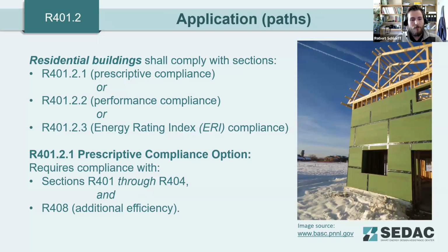Moving on to more of the standard non-above code. So these would be the compliance pathways for the Stretch Energy Code as it is without going above the code. Similarly to the base state energy code, the base IECC, we have a prescriptive compliance path, we have a performance compliance path, and we also have an ERI or energy rating index compliance path. All three of those are formulated very similarly to the IECC paths. So again, borrowing language, borrowing structure from the IECC.